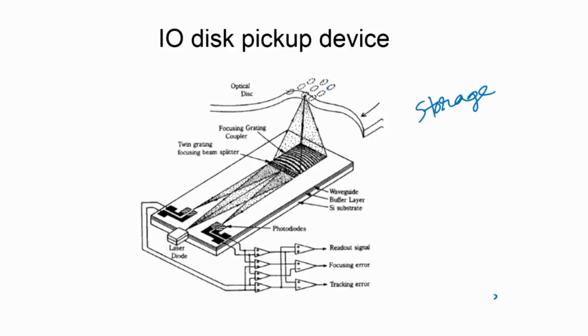You have a laser, and this chip has a grating, which is the crucial element. You have a focusing grating which can focus onto these bits very accurately, and it could be designed such that it can address any of these elements. The movement of the disc could also be arranged such that the bits are accurately aligned with where the spot is focused.